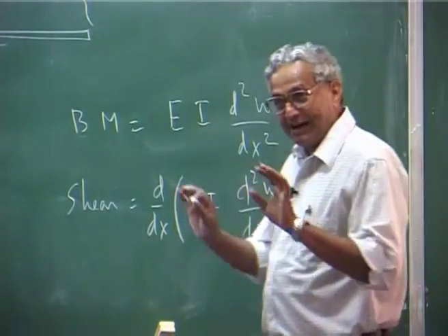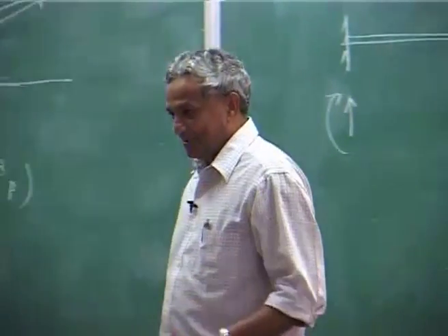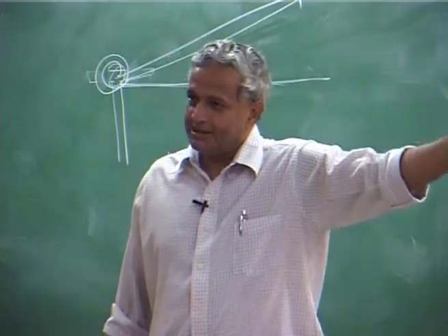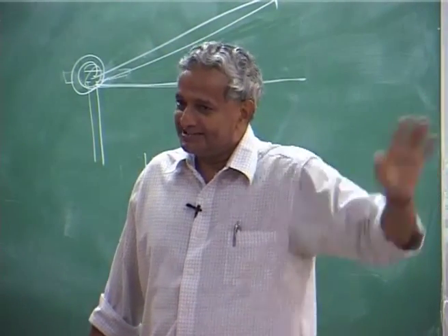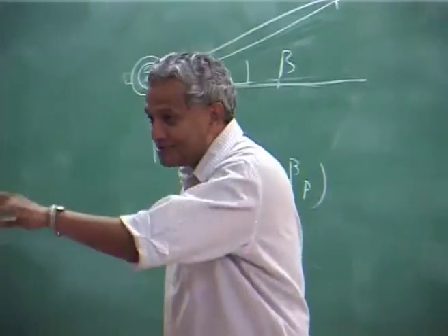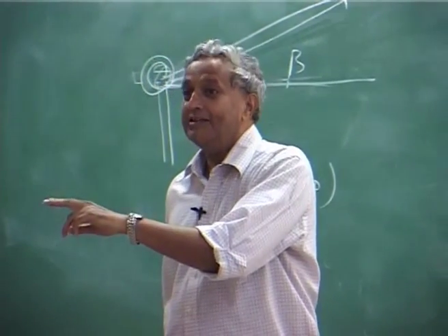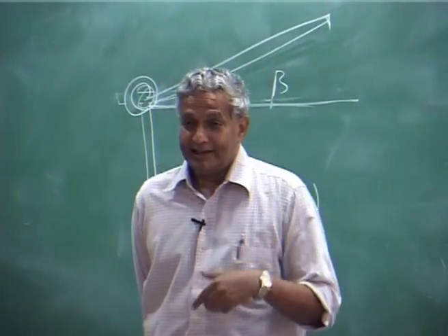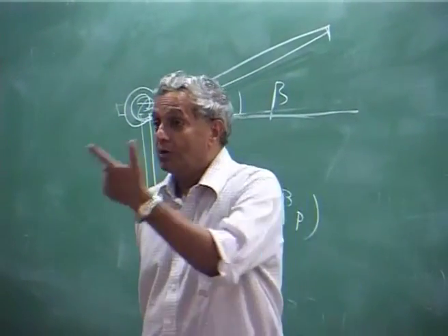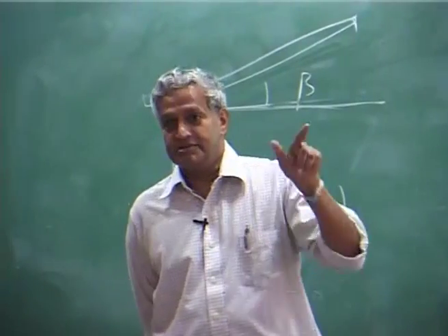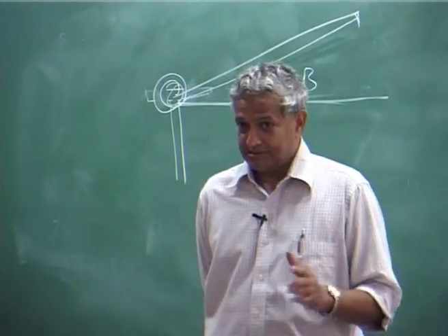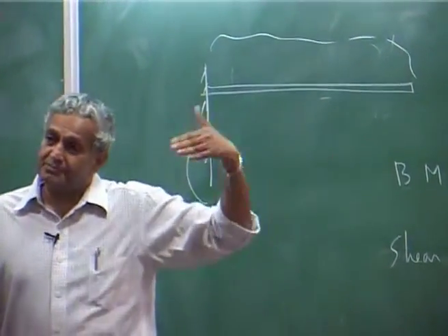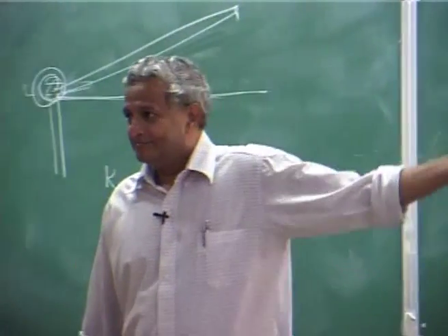One is to take the applied load, integrate the load, and get the bending moment and shear at some section. Another is to solve for the deformation and then take the standard relations. In an aeroelastic problem, the applied load is a function of deformation, how much it deforms.